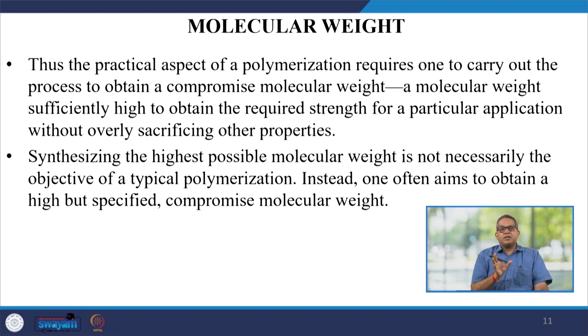Now see, this is an art, because the polymerization process is an art to make the monomer polymerizable. The second thing is that you created a polymer, but to make that particular polymer processable, that is again an art. At what time you need to truncate the reaction is an art, so that this particular polymer must possess the molecular weight which is required to have the proper strength and proper properties. So, this is an art.